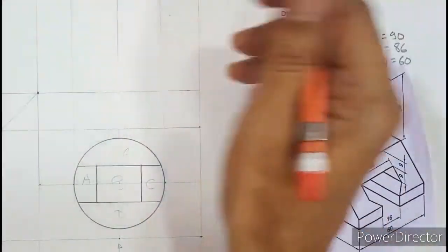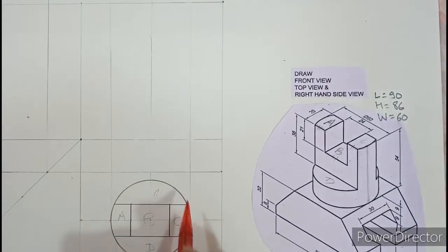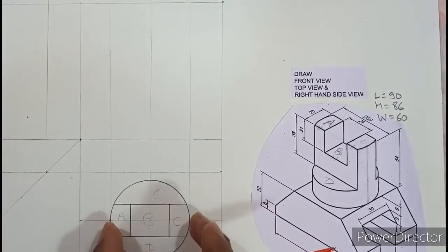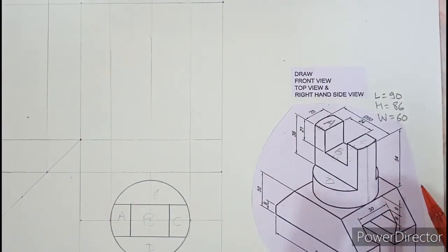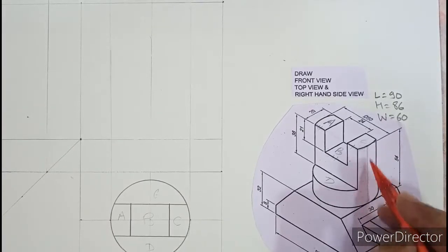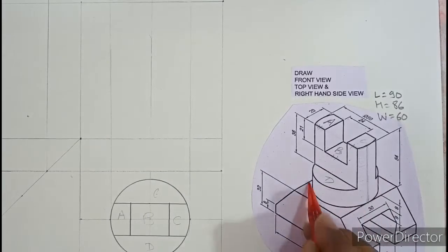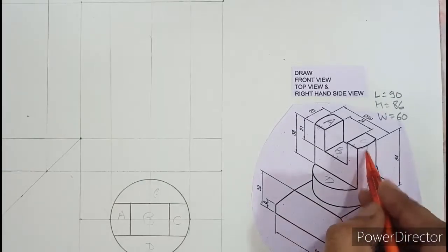Yeah, so that is how this cylinder is projected up. Once this cylinder is being projected, the boundaries of A and C were projected up, and as per the question the height of the cylinder is 54. So you can see this boundary up to 54 millimeter, isn't it? And then the bottom edge will be seen as a straight line. The circular edge from the front will be seen as a straight line, and you can also see this boundary.